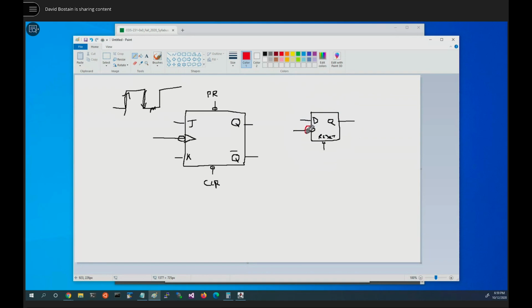We know it's got to be a flip-flop. It's got edge triggering. Edge triggered, falling edge. So we know that if we have a clock whooping along like this, the thing's going to actually be triggered on that falling edge, on the next falling edge. That's the only place it's going to be triggered.